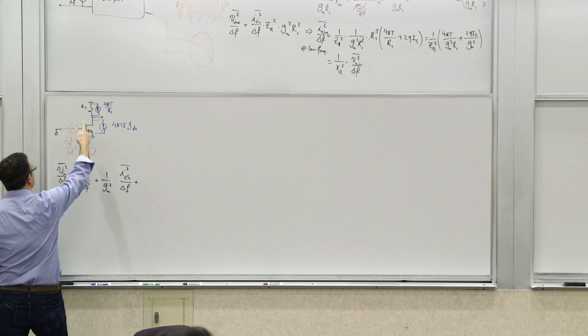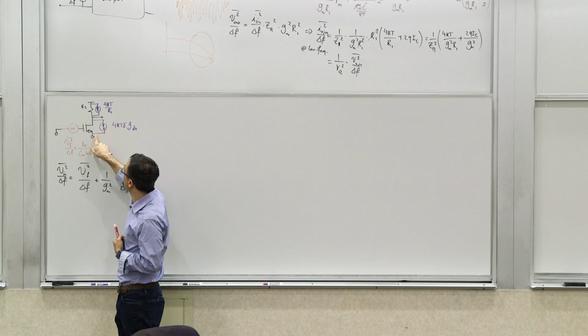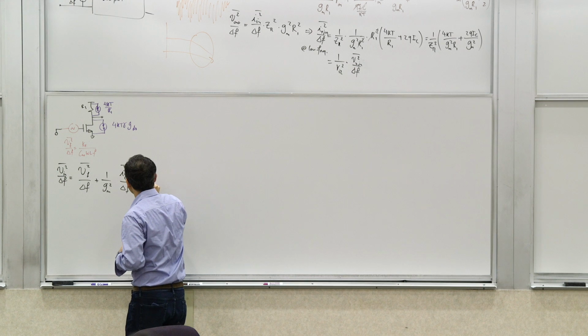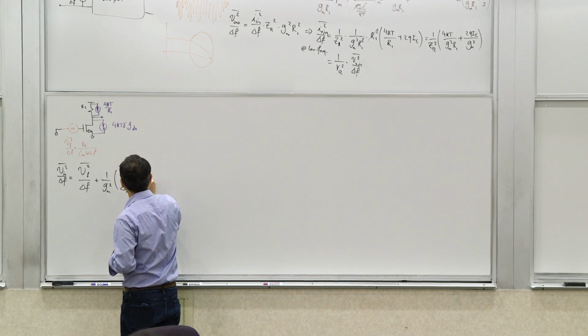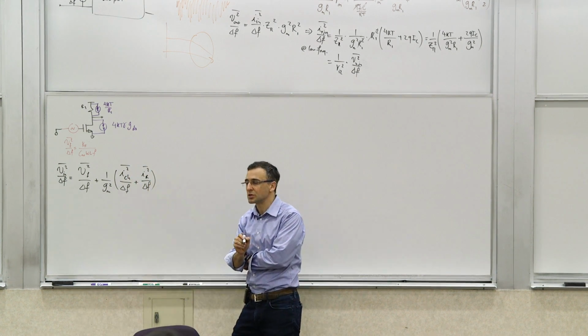Plus, then how about the resistor? The same deal. It's the same current, right? Because it's a current between a ground, because this is AC ground, and this node. So again, it goes through the same transfer function. You can actually, in fact, write it as I res R squared over delta F. So that's my input referred voltage noise.